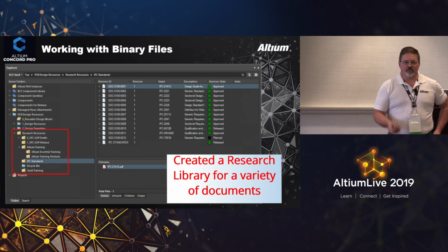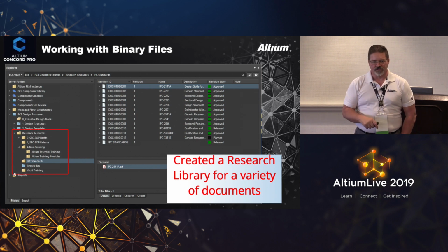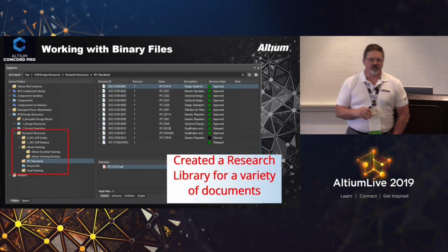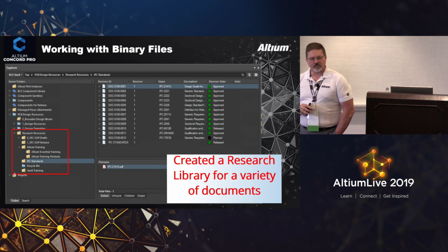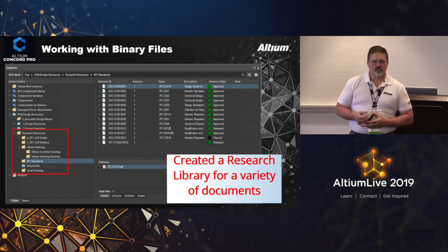Yeah, remember, in your parameter information in that component, you can put anything you want. You can put links, you can put hyperlinks into different other areas. So we actually can link data sheets to those components, in any of those parameter areas in the component itself. Is that something in revision? I think it does. You're changing the parameter so it would change the revision level, but that's not a big deal. It's just, at the end of the day, when you've got your design, you're doing that final check, maybe there's something like that.